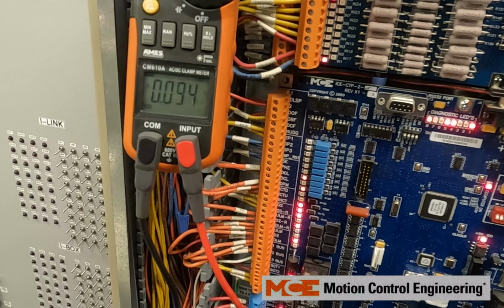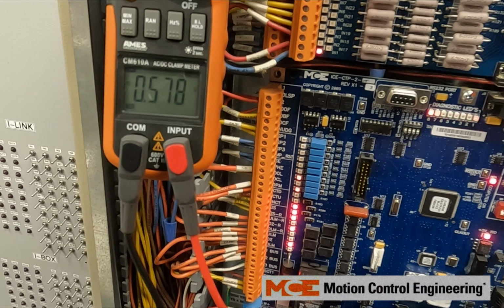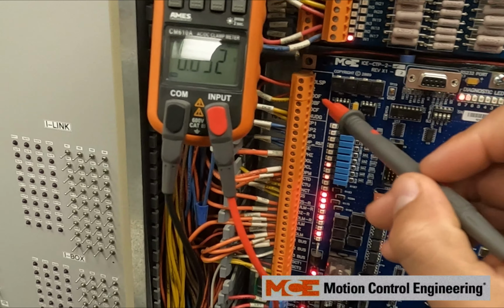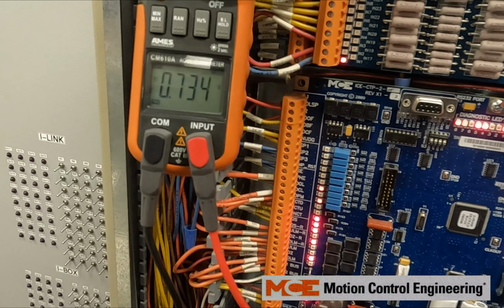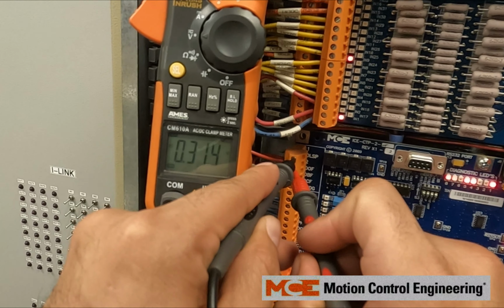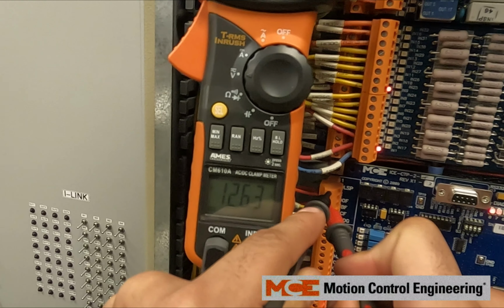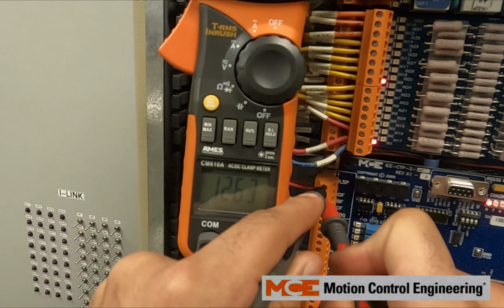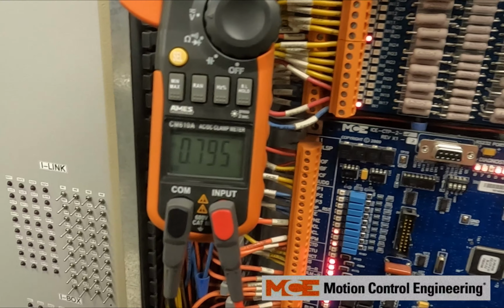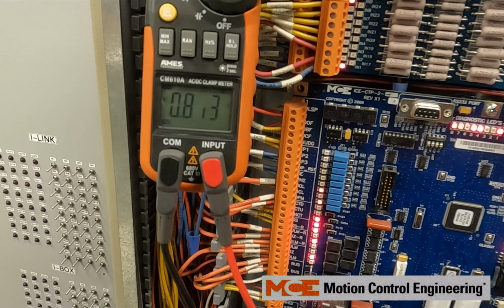If you're not getting any voltages for anything, you want to make sure you have car top communication as well. And you want to make sure that you have voltage all the time from common to DLSP. You can tell we have 126 volts AC there. If we don't have our voltage there, then we want to look at our I-Link connections to make sure we have our 2-bus. Make sure no fuses are blowing as well.